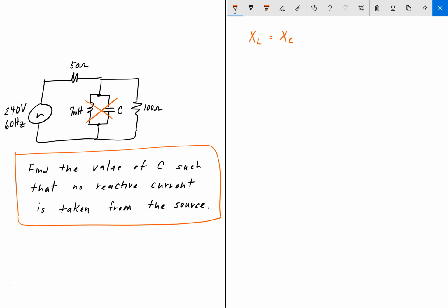When the capacitor and the inductor are in resonance, they oscillate energy between each other. The inductor gives energy to the capacitor, and at that same frequency, the capacitor absorbs that energy and then sends the energy back to the inductor, and they oscillate back and forth, sharing this energy. Essentially their net reactance is going to be zero, and the circuit becomes purely resistive.